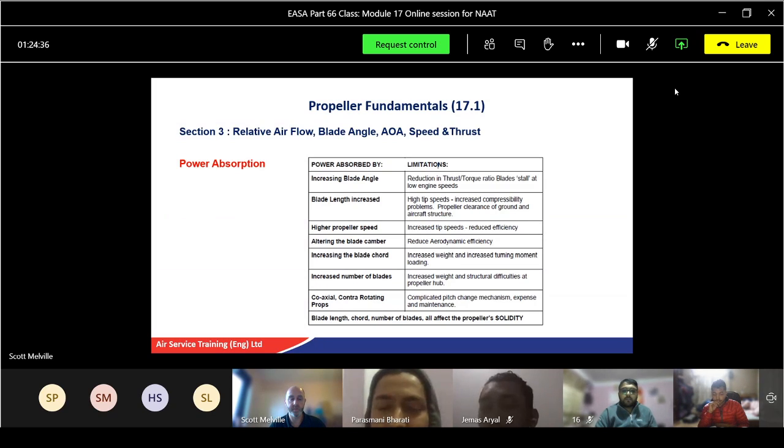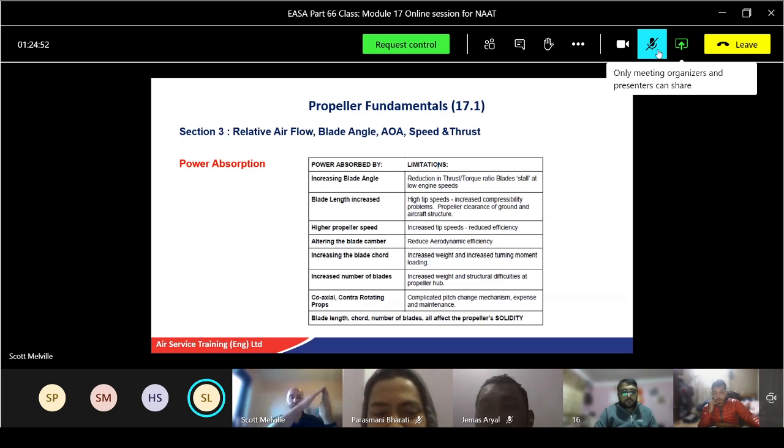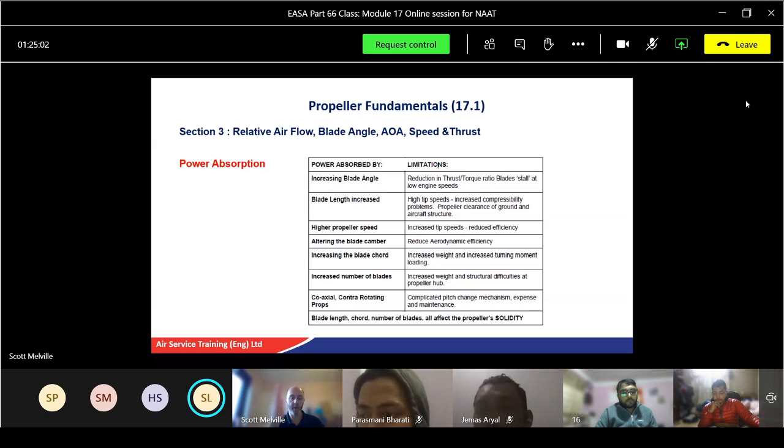Decrease, yeah. Because the aircraft's trying to catch up with the propeller. The aircraft's going faster, so the angle of attack between the relative airflow and propeller will decrease. So if the angle of attack is less, your blade is now almost in a fine position, so it can cut through the air nice and easy, which goes faster, which is good, a little bit, but too fast and we can overstress the engine. Good.